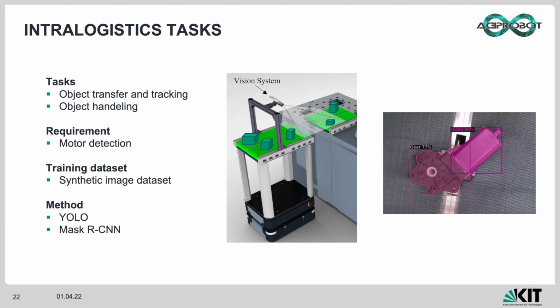Detecting objects and estimating their pose is essential to realize the decentralized control between the autonomous mobile robot and the transfer unit. In our case, by feeding generated motor models to Blender to generate static image data, one can create high-quality re-rendered images with accurate ground truth annotations. Enriched with labeled real-world images, one can create a dataset of reasonable size to train well-performing real-time detection and tracking network models.